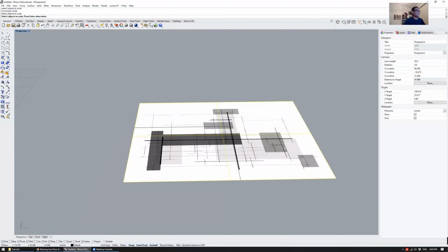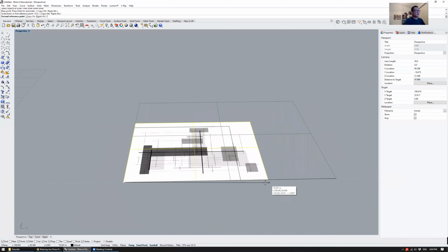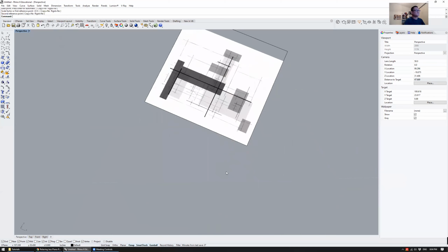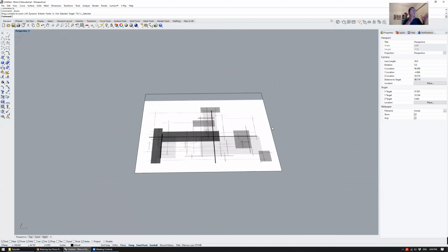Select the diagram, enter, base point, our lower left. Now we're going to give it a first reference point. So I'm going to go way out here to the lower right corner, click, and then you'll see that now I can match this to a specific size, like that. Okay, so now I know this is sitting perfectly within the 15 by 15 square that we want. All right.